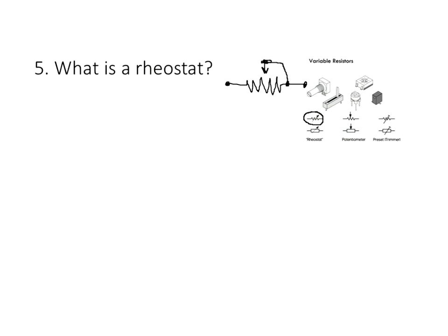Okay, now some questions in the CET will revolve around your understanding of a rheostat. A rheostat is wired like that. When you see it wired like this, it's a rheostat. Another way that you'll see it is you'll see it wired to the other side, over here, like that. When you see a variable resistor or a potentiometer wired like that, it's called a rheostat. And a rheostat, you're actually using two wires, this one and that one. Okay, so that's what a rheostat is. A rheostat is a potentiometer wired as a pure variable resistor.